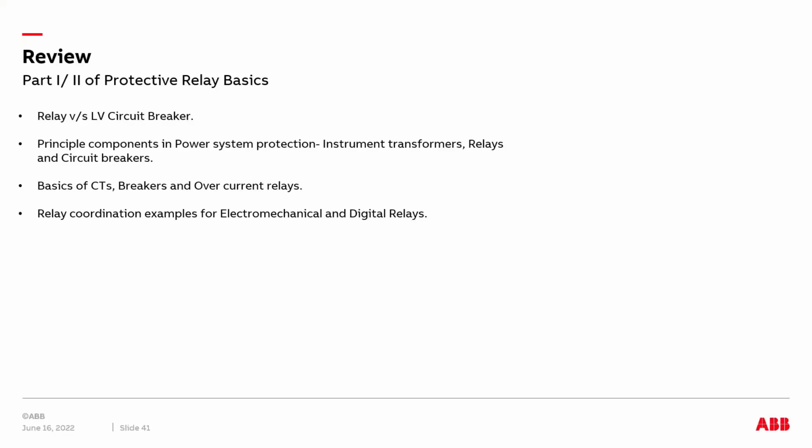We also saw what are the principal components in medium voltage power system protection, which is instrument transformers, relays, and circuit breakers. So instrument transformers feeding us the information of the current and voltage into the relay, and the relay taking the action on the circuit breaker.